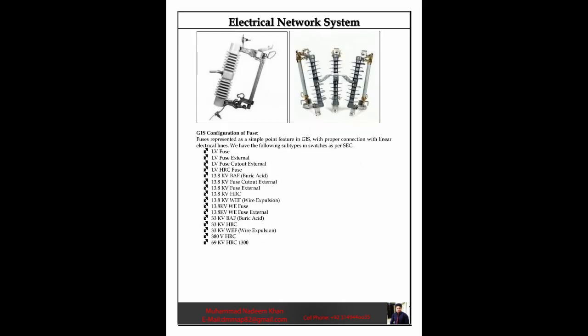GIS configuration of fuse. A fuse is represented as a simple point feature in GIS, with proper connection with linear electrical lines. We have the following subtypes in switches as per SEC. LV fuse. LV fuse external. LV fuse cutout external. LV HRC fuse.